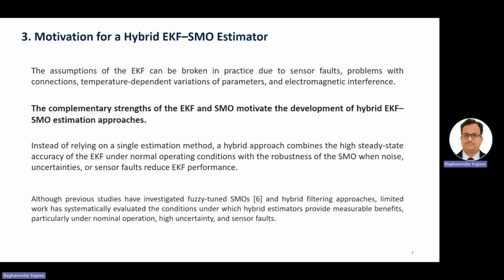What is the motivation behind taking a hybrid model, such as EKF as well as SMO? In this research, we came up with an algorithm that will use both EKF and SMO estimators, but not at the same time. They will switch between these two, depending upon the SOC conditions.